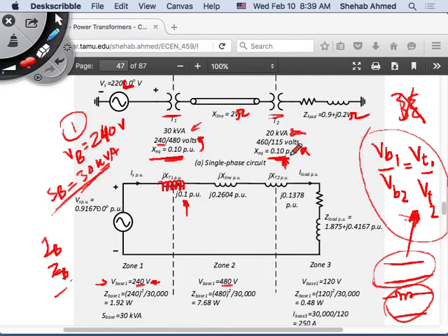Okay, so let's see how we will deal with it. But is this one understood? At least this one we will just bring down here. We don't need to do anything about it. So we put our line here at the transformer, and then we calculated the voltage base here. Now let's calculate the voltage base here. We'd like to see how they came up with this 120. Because this transformer is 460 to 115, and my base here was 480.